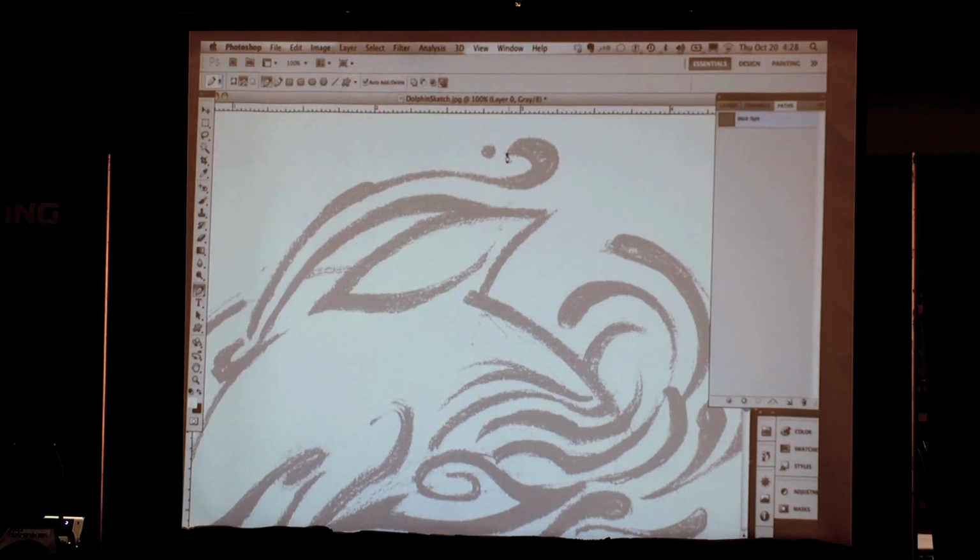I'm going to click it once. And these are Bezier handles. When I move over a little bit and click my mouse, while I'm holding my mouse, I'm going to pull out this handle. That's called the Bezier handle. That's a curve that allows us to shape that line into any direction that we want to go. So if I do like this, and I'm going to roughly trace my original sketch, I can click and let it go.